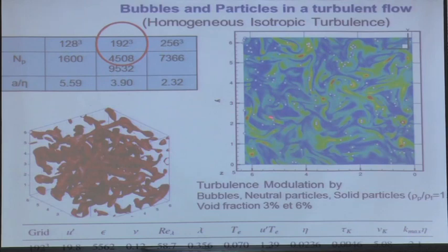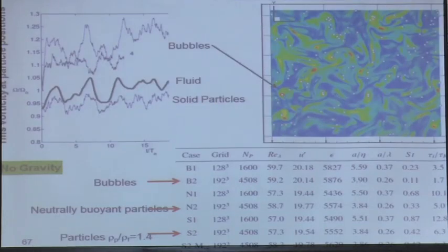And then we placed particles into that flow. So each particle is resolved by 10 grid points. And then we have full access to the effect of particles on turbulence. I told you that there is an open question: does it enhance or does it damp the turbulence? And with that type of simulation, in a very academic system, because it's only a cube of fluid with no walls, nothing, then you can see what the effect of particles is, for example, on the agitation of the fluid. So you can do the same simulation single phase, with particles, different densities, different sizes, and then you compare the response of the flow due to the particles.